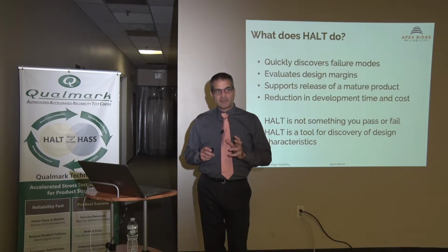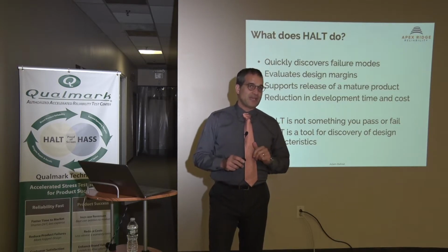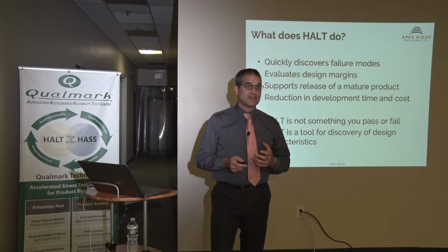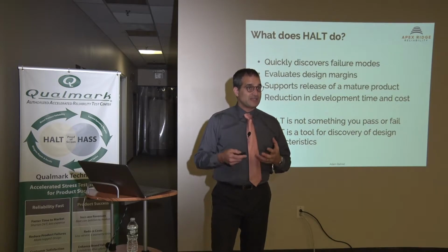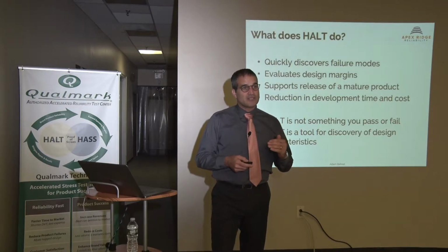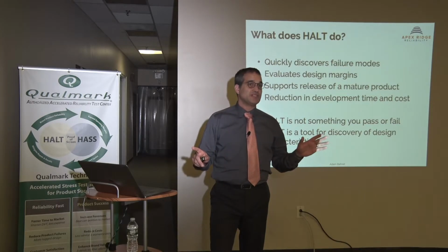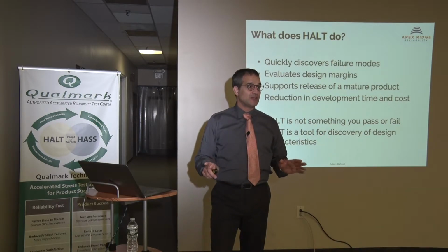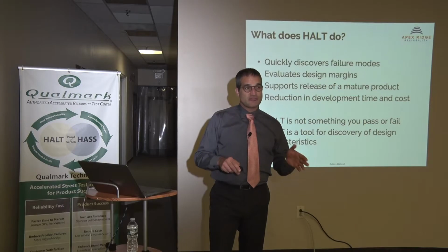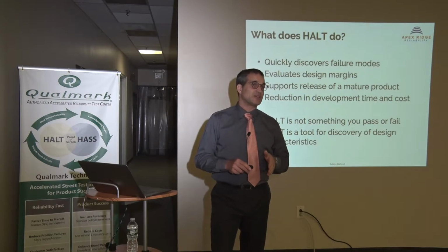One of the other really fundamental parts of it that's important in understanding it is it's not a test you want to pass, which is hard. We all want to pass tests. We've been taught to want to pass tests. And a lot of engineers take a lot of personal pride in their designs, and they want to pass tests so they can progress through the program. Well, HALT, if you've passed it, and by passing I mean you haven't experienced failures, completely wasted your time. There was no reason to do it at all. You want to fail. It's the failures and an opportunity to observe the failures, understand what occurred, and then use that as input to ruggedize the product early.